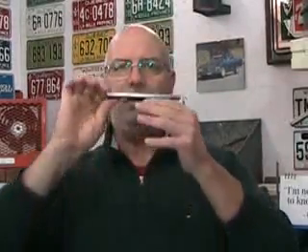How would I obtain this? Well, quite simply, because it's a simple example, it's something we can relate to. Well, if I were to mount this on an angle plate and grind one surface flat, and then use that surface on the magnetic chuck of a surface grinder, support it with a very square block, and grind the second surface, well, my two surfaces would be quite parallel.